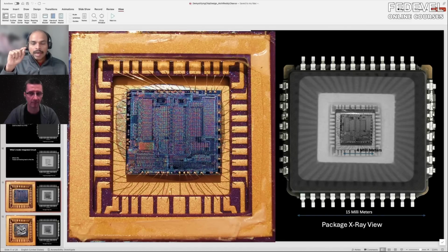Now, like you pointed out, there could be an issue with the bonding wire, and if that is the case, for that particular bit we don't read any signal. You pass a pattern, and you know how many bits you're sending, how many bits you're reading, and what the expected value is. That's one of the reasons, for example, why JTAG exists.